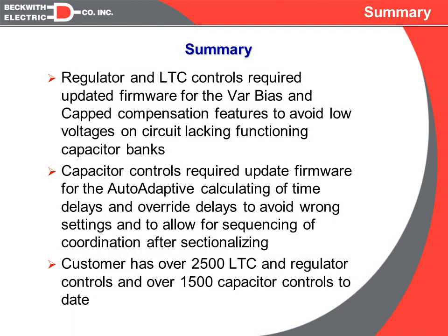So in summary, the three main problems we had were solved by, first of all, placing new algorithms in the LTC and regulator controls via VAR bias and capped compensation, so that we could limit the effect of the compensation when we have the lagging power factor, so that we don't have low voltage conditions.